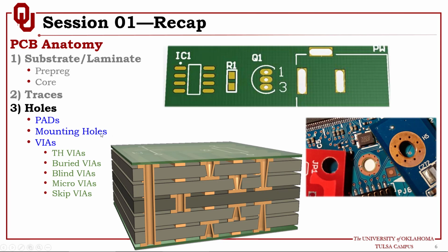Mounting holes, sometimes they call them mechanical holes, as we can see in here, and they are only used for mounting the boards or fixing the boards and stuff like that. They are not connected to any traces, and they don't have any electrical characteristic other than being mechanical holes, and the copper is just to add rigidity to the board at this point. Instead of having it, sometimes you can remove the copper and have it on only the fiber.